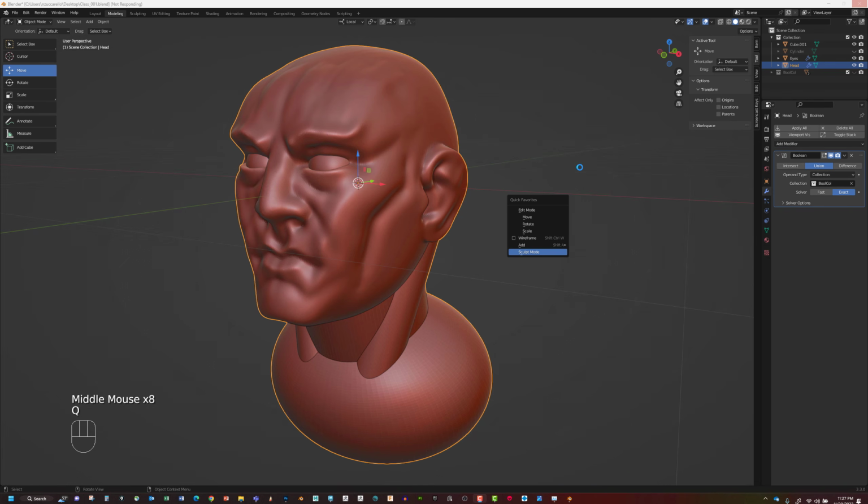And I do understand why it's taking a while. This is a new mistake of mine because I'm a bit new to this. Before I went to sculpt mode, what I should have done is just apply this Boolean modifier. So I believe it's attempting to process that all over again, which is kind of disappointing because that took about, I'd say, 4 minutes to run through. So I'm going to have to let it go through, and if I mess that up, I'm going to have to come right here and go back into object mode and apply that. I don't want to make you sit through that mess.